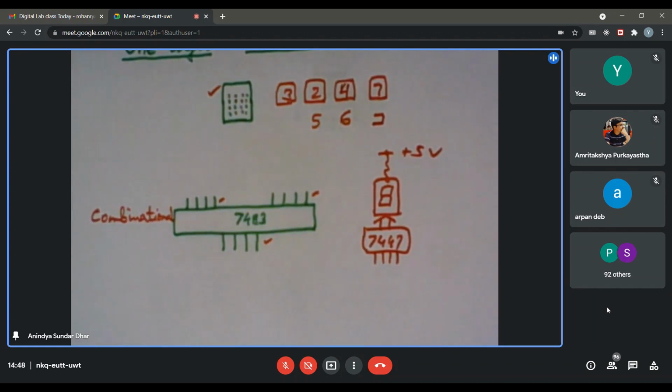In this case, maybe we are talking about, say, if I say 4-bit register and 8-bit register, so it would be able to so-called register a 4-bit number or 8-bit number. It can store that one for some time. So it is not a combinational circuit, it's basically a sequential circuit. Whatever I put at the input, it can memorize that one till another clock pulse comes. And if I have changed the input by that time.